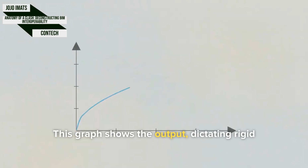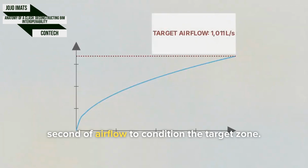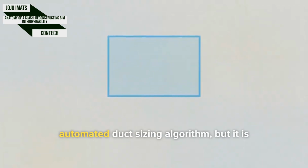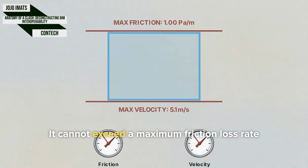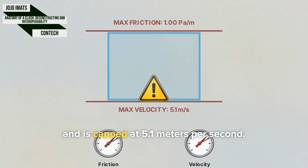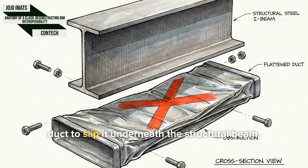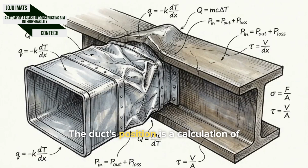This graph shows the output, dictating rigid cooling requirements, a mandatory 1,011 liters per second of airflow to condition the target zone. The BIM platform uses this target to drive an automated duct sizing algorithm, but it is constrained by limits. It cannot exceed a maximum friction loss rate of 1.00 pascals per meter and is capped at 5.1 meters per second. The engineer cannot shrink the height of the duct to slip it underneath the structural beam. Doing so would choke the airflow and violate those friction and velocity constraints. The duct's position is a calculation of thermodynamic requirements.